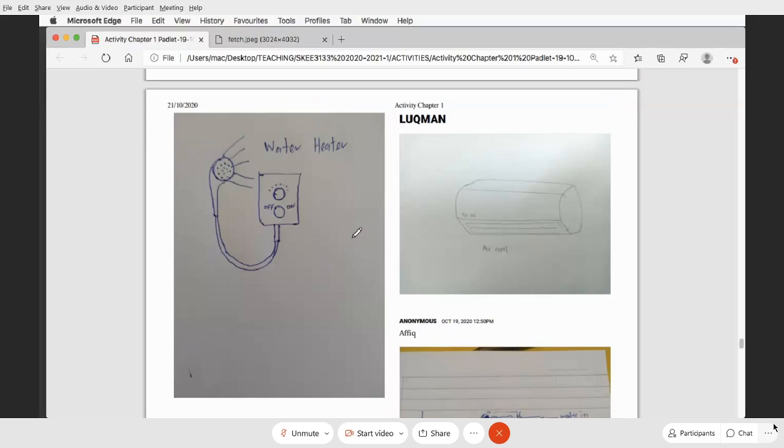The expensive one maybe uses an AI technique, but the cheapest one uses on-off. Where it is over the limit, it will turn off. Below the limit, it will turn on. So it is still a control system, but the controller itself may be cheaper. On-off is something like a switch. So it is closed, right? Yeah, closed loop system. Still automatic.